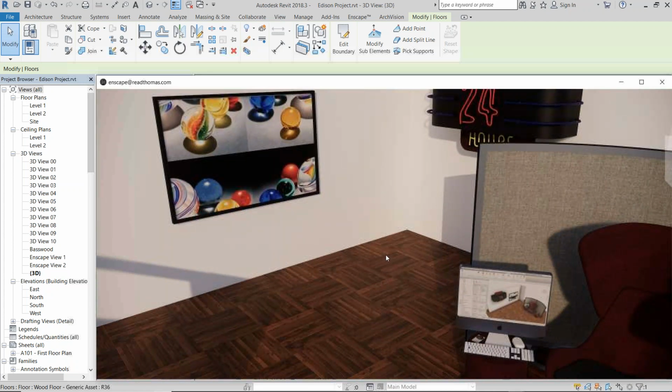I don't like using the decal tool because decals are host dependent. If you apply a decal to a wall, or a lot of decals to a wall, and then that wall is inadvertently deleted, all of those decals disappear, and you'll have to manually go back and replace each one, get it the right size, and then hope that nobody deletes the host again. So instead of using a decal, I would recommend just building the component family and applying the image.